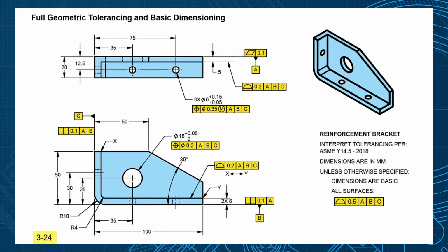So remember, position controls the holes. We float that underneath the size tolerance, so that creates a cylindrical tolerance zone for the hole. Then this position tolerance, those will create cylindrical tolerance zones for these three holes. And in this view here.